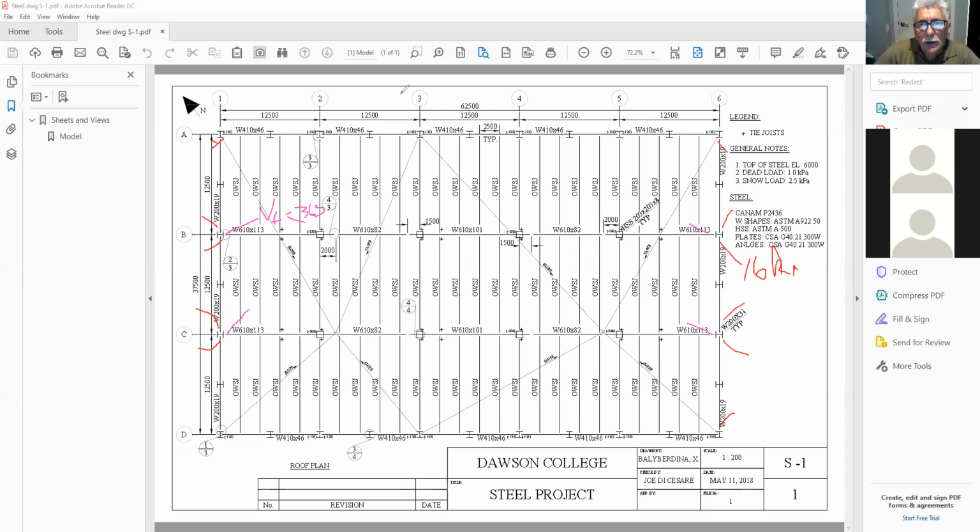Then the third one was, let's make it in green, the third one was here, here, here, you understand? And these ones here we said were on the wrong side of the beam. We said this one was 40 kilonewtons, and that's what you designed that for. All I'm saying is that here where you have the two beams going back to back, when you're checking the thickness of the web member for the column to make sure it has the right material, remember that your VF force here is 80 kilonewtons. So you have 40 on this side and 40 on that side. So this thing has to resist both sides. That's all I'm saying. Okay?